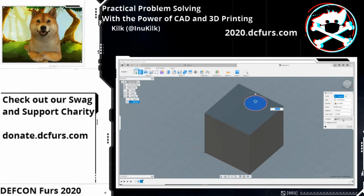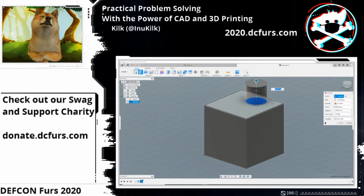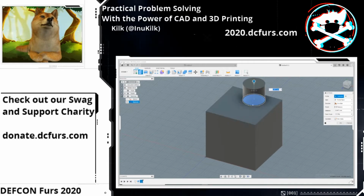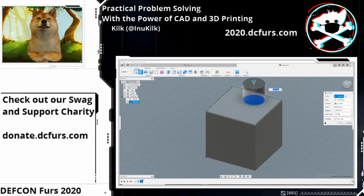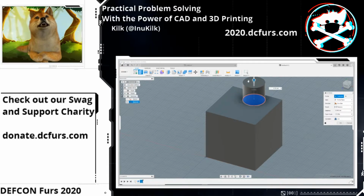When we did the first one, we did a new body. We were creating a new object based off of that sketch, like imagine pushing material through the sketch. But this time we're doing it off of a sketch on the face of the object, where you could do join instead, because we're joining these two together.